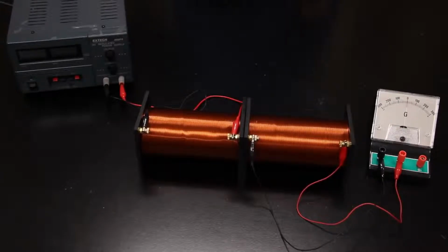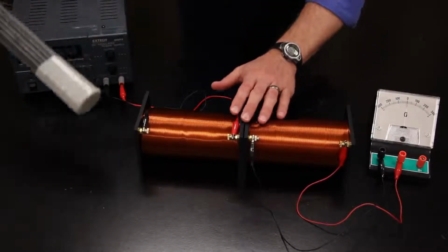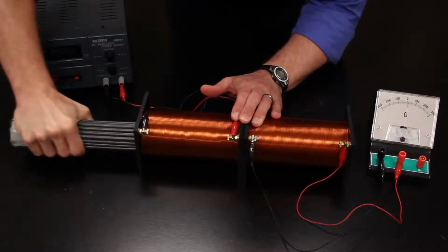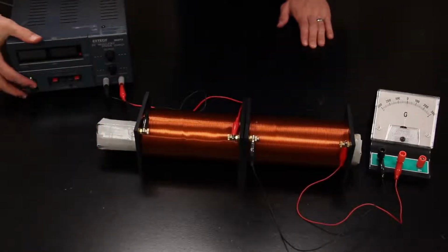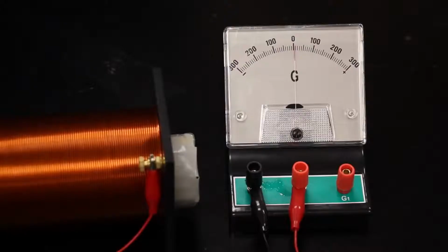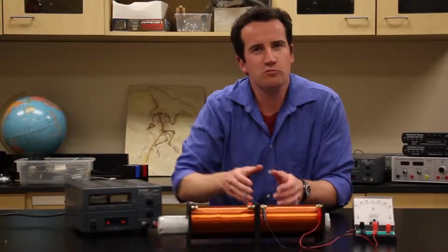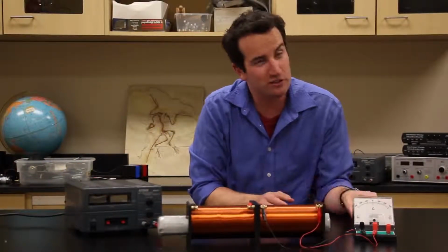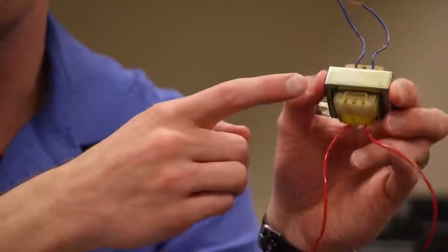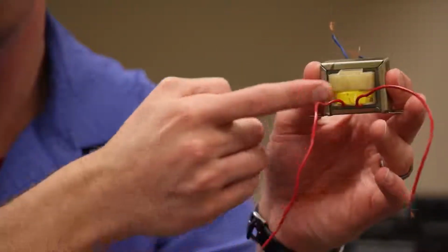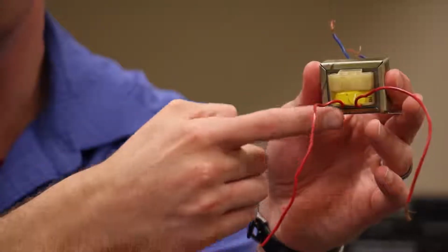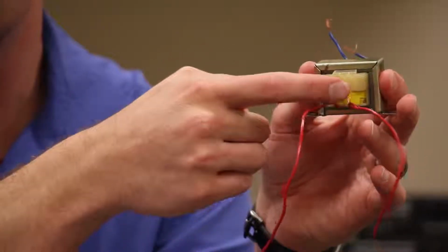The magnetic flux between the coils is greatly increased when a soft iron bar is added. This improves the efficiency of the transformer by strengthening the field and preventing it from diverging out and being wasted. Whoa, much better. The transformers found in home appliances usually look like this. Here are the coils, which are wound on top of one another, and this surrounding structure is soft iron shaped to guide the magnetic field lines back around and through the coils.